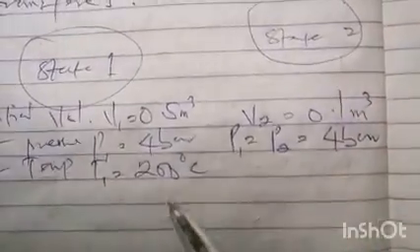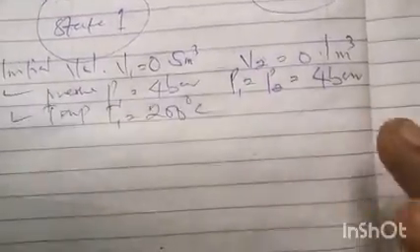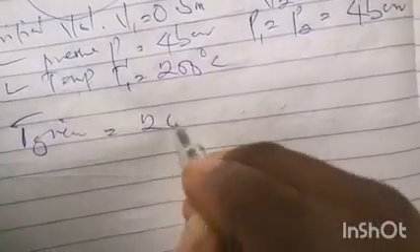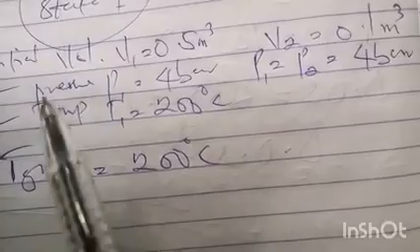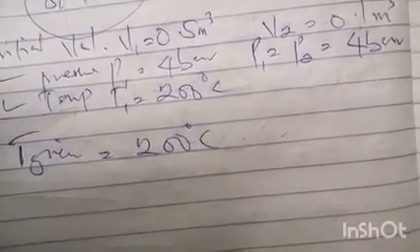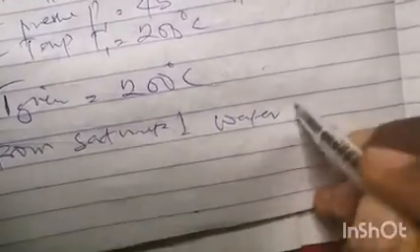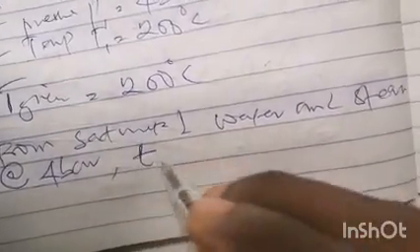So of course we'll use the condition of the steam at state 1 to find the mass of the steam. Okay, so temperature is given as 200 degrees Celsius. That's at state 1. So what we'll do now is to find the saturation temperature at this pressure and see if this steam is actually superheated or saturated. So from the saturated water and steam table, corresponding to 4 bar, that's the given pressure, let's find the saturation temperature now.